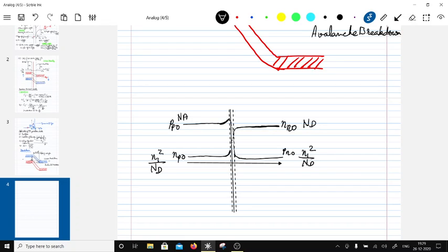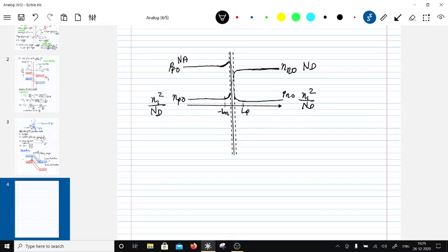Okay, so now what is the source of this current? Or rather it is the reverse way. The current causes these slopes, so basically these slopes are indicative. So let's say there is a point which is minus ln, where the excess electrons basically become equal to the bulk, and similarly over this side there is LP, where the same happens. So now the Fermi-Dirac relationship gives you the density at x equals 0.